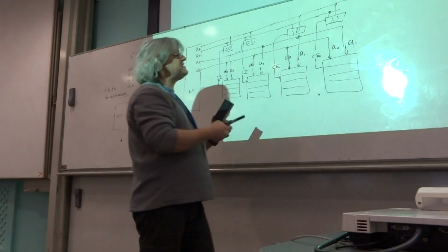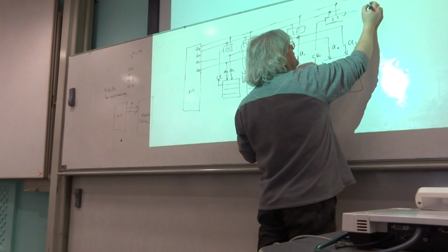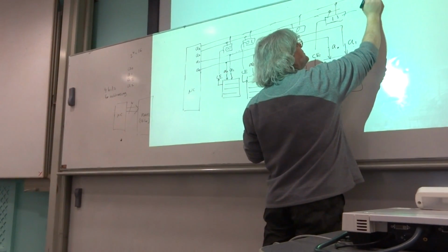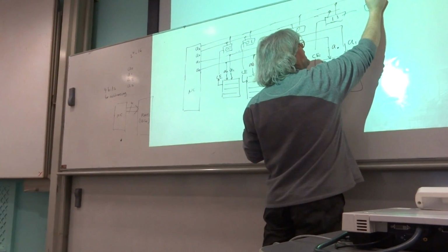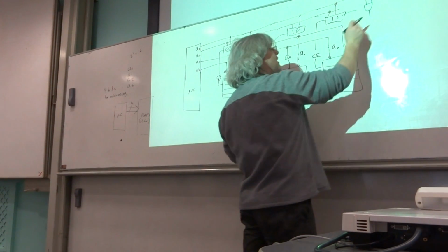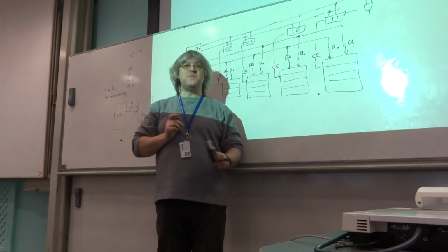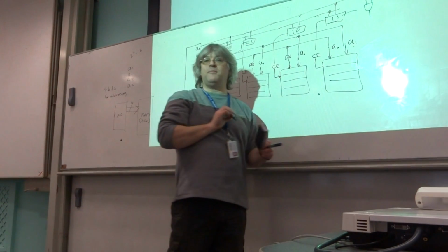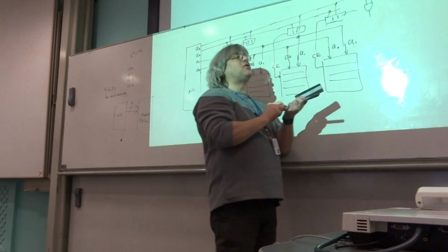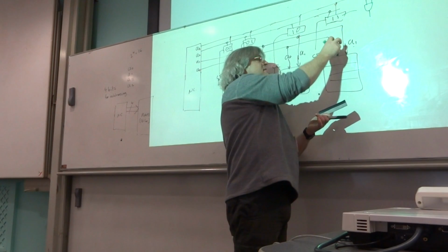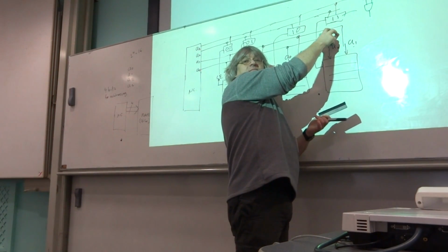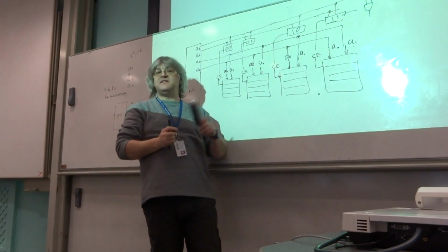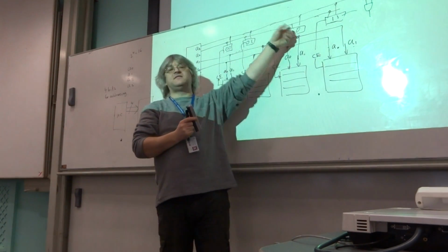Now, in the case of this one, it's easy. In the case of this one, an AND gate would do, because it would just be A2, whoops, that's not how you write 2, A2 ANDed with A3. Only when both of those are high will that basically switch on. And for all of the other combinations feeding into that, that will be low. That's precisely what I want. It's only when that magic combination 1, 1 appears that this is going to wake up. For all the other combinations, it will be asleep. And there'll be other logic gates that I could put in there to achieve the same kind of effect.